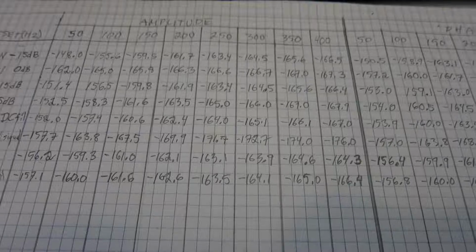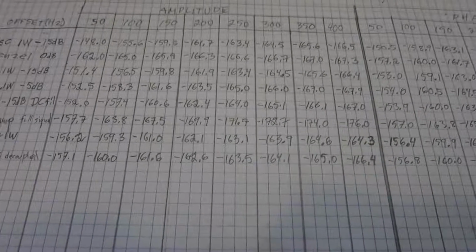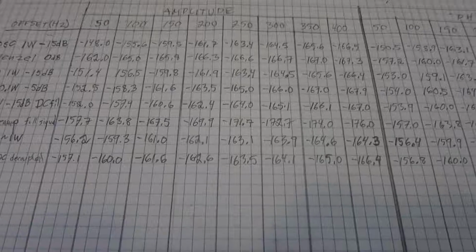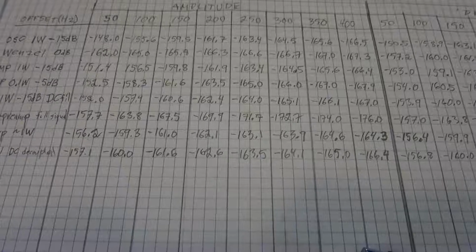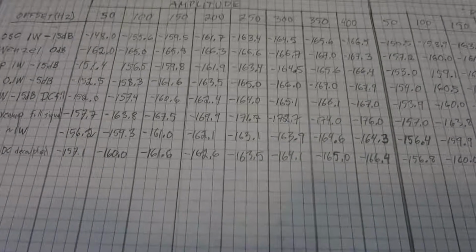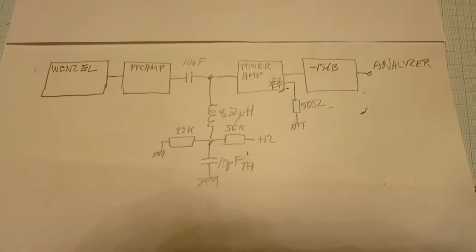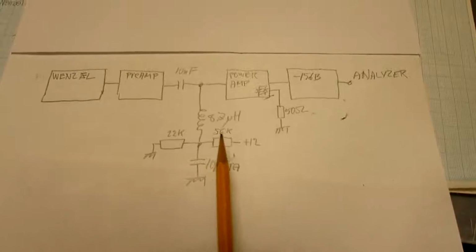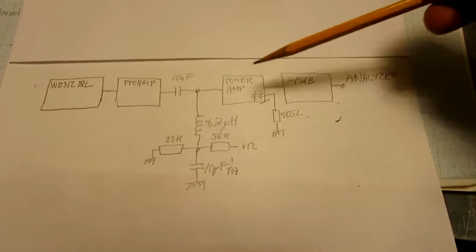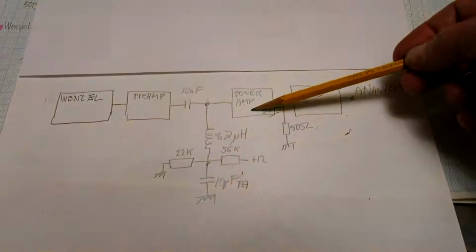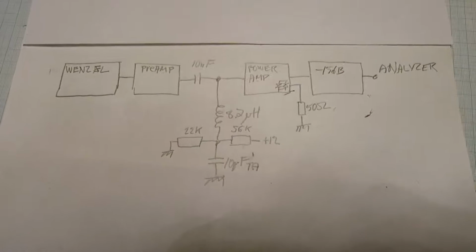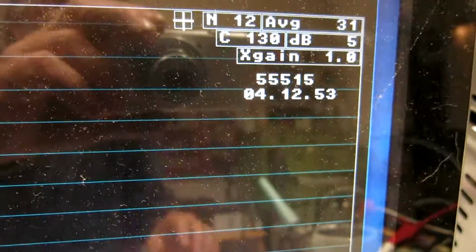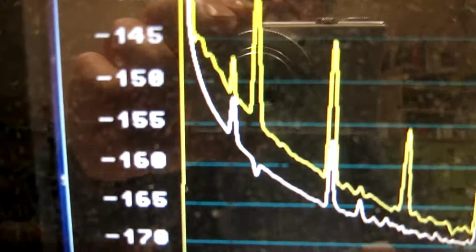So anyway, having a separate voltage divider properly decoupled for low frequencies to provide the DC bias for the power amplifier will be a good idea. I have now arranged a separate voltage divider for the base voltage of the power amplifier, and this gives a small improvement. I have been running for a little more than 4 hours, and here is what it looks like.